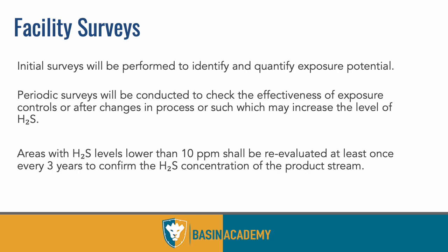Facility surveys. Okay, so moving outside of the first aid side, companies are required to test their wells for H₂S and then communicate that information to contractors. They don't have a crystal ball, though, so they don't always know what future wells will become sour over time, and it does happen, as I mentioned before, through communication with other zones, fracking, different things can cause a well to become H₂S over time. So they should be testing these wells at least every year, every 3 years, depending on their plan, and then communicating that to subcontractors. Anything over 10 parts should have a breathing air system on there.